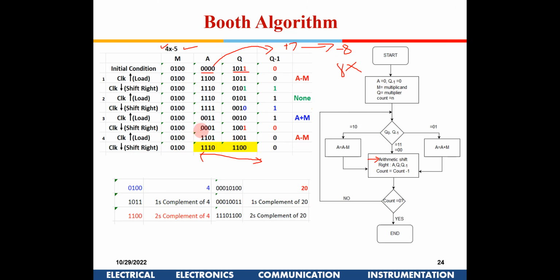Here I am making a shift operation, so 0 is being inserted out here, right? Here again I am making a shift operation. If you see here, it is not a 0, it is a 1 which is being pumped in here, right? So this is an arithmetic shift operation. So you have got to take care of that also. Is it okay? Okay, sir.